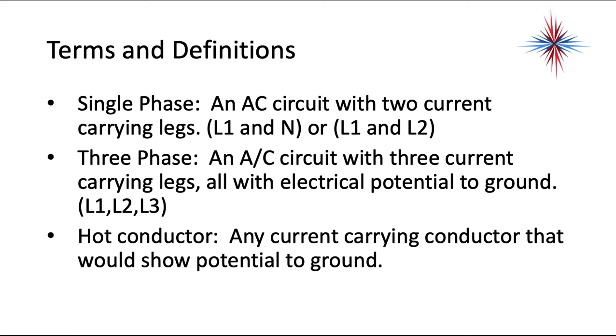Single-phase. It's an AC current with two current carrying legs, L1 and neutral, or L1 and L2. Three-phase. It's an AC circuit with three current carrying legs, all with electrical potential to ground, L1, L2, L3, and I'll explain more about that in a few minutes.